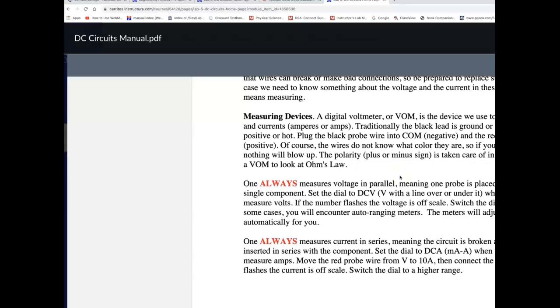All right. Now, for the measuring devices, we are going to measure the voltage. And today our measurements are DC. And we are going to measure also the current. Now, polarity is important. What does it mean, polarity? Polarity, you must connect the black to the negative and the red to the positive. If you switch these terminals of the multimeter, you will get a negative number. Then, of course, you should have your numbers positive.